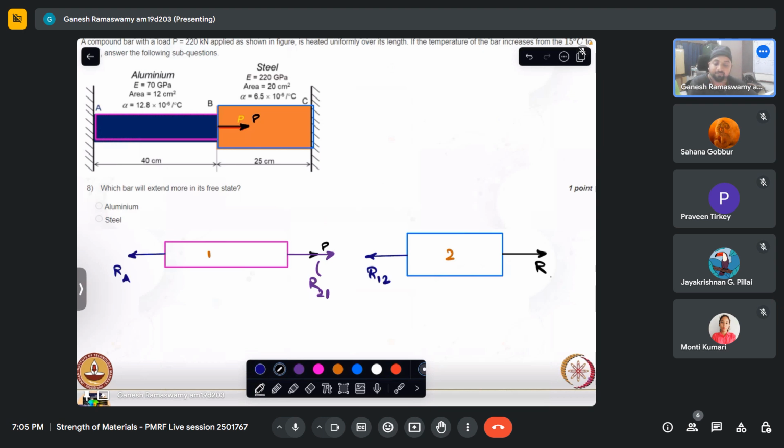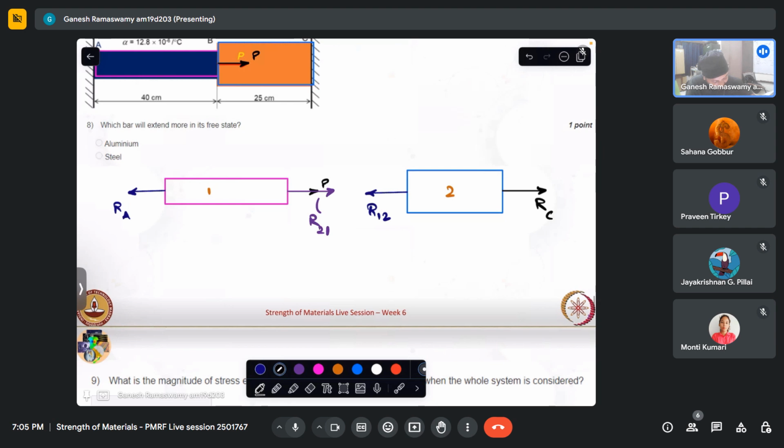So now we have essentially drawn the free body diagram with all the components filled in. Is it necessary that this force would have to be this way? No, we have assumed it that way. And based on our computation, if it comes out to be negative, it would just imply that we need to reverse the direction instead of following the same direction. So far, so good. So for body 1, now that we know by Newton's third law that R12 is equal to minus R21, I can drop the subscripts here.